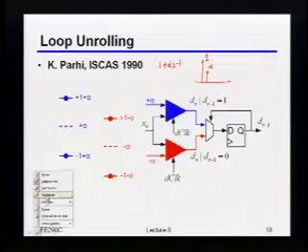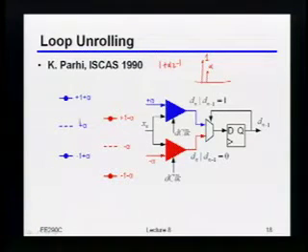So the visual mapping you're supposed to get from this picture is that if the previous bit was a 1, that's like saying that what I'm sending this bit will be shifted up by plus alpha, right? And if the previous bit was a 0, then what I'm sending this bit will be shifted down by minus alpha, right? So it should hopefully be clear that if you take these two comparators, one where you've shifted the threshold up by plus alpha, then that's as if the previous bit was a 1. And if I shift it down by minus alpha, then that should be the correct slicing point if my previous bit was a 0. Okay?